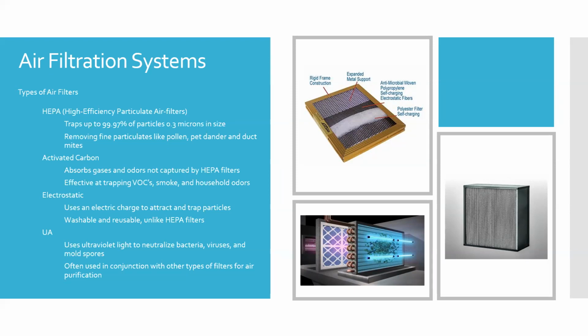But then you have electrostatic filters. Those used to be more popular in the past. I don't really see a lot of these. I think you can order a lot of them online. I used to sell these exact filters that you see here, with that metal frame. Basically, it's an electrically charged media filter that attracts and traps particles. Most of these that you see are washable and reusable. As you see in this little picture, they use self-charging electrostatic fibers, so it's not powered by anything. You don't have to plug it into anything. It basically self-charges as particles go through it.